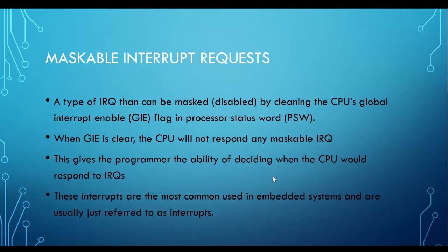Let's say, for example, you have a pin. And when this pin receives 5 volts, it goes into the interrupt routine. But sometimes because of power instability, you have a lot of interrupt requests that are actually not valid interrupt requests.